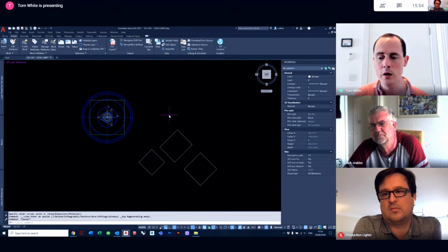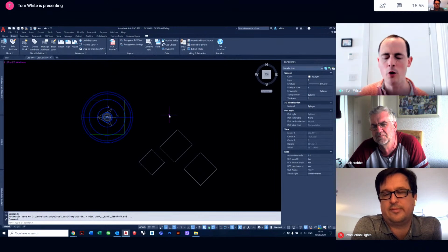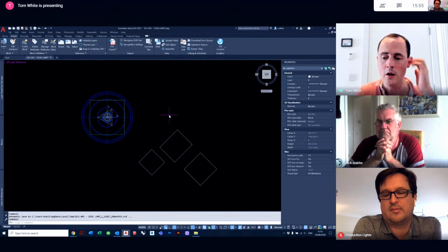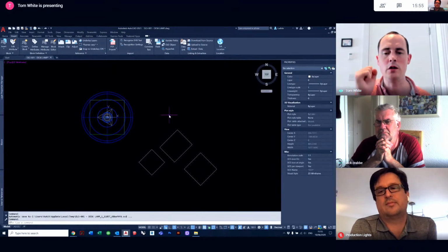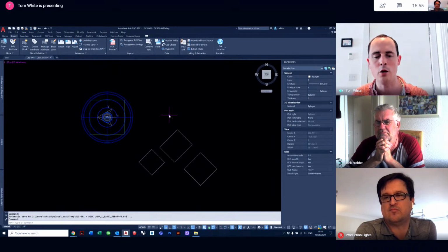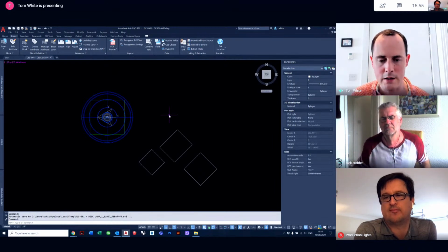Yeah, and another good practice: if I had my theatre and Dom had done a lighting plan of it, it would be hugely beneficial if Dom had an X or a circle on the UCS, just in case it changes. I XREF in the lighting plan, and I don't want to move that XREF around, because that would be a negative thing. I'd go back to Dom and say, excuse me, Dom, I think there might be a little bit of an issue. Could you move your lighting plan back to our agreed world coordinate system?